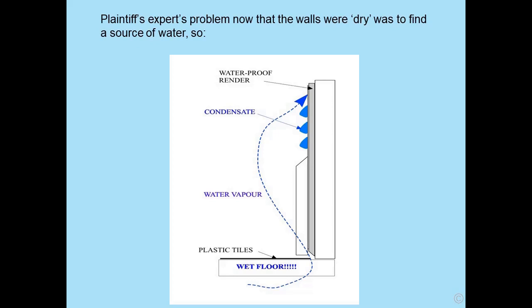In other words, condensation was happening, and should have been happening because of the below dew point temperature. So what he's now saying is that water is evaporating from an area where it should be condensing and then recondensing on the wall. Well, quite simply, this is rather nonsensical.